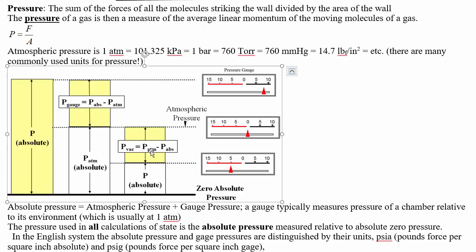There's also vacuum pressure, which is the opposite of this. It's negative gauge pressure. So you could say that we've got maybe 50 kilopascals of vacuum pressure. Maybe that's a bad number because it's close to half of this anyway. 20 kilopascals of vacuum pressure would mean that we are 20 kilopascals below 1 atmosphere. For really high vacuum, this becomes inconvenient. So you're talking about 101.2 kilopascals of vacuum pressure. That's not a very good measurement. So most of the time for high vacuum systems, they actually measure absolute pressure.